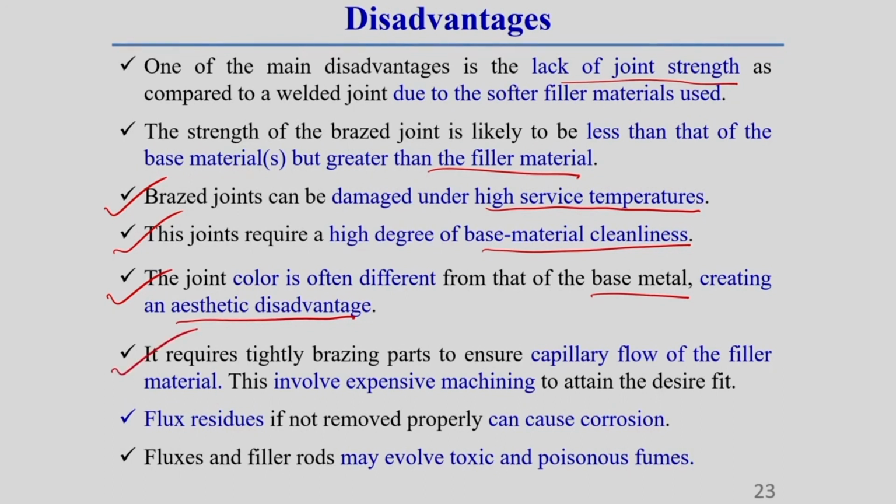It requires tightly fitted brazed parts to ensure capillary flow of the filler material. That is why this involves expensive machining to attain the desired fit. So, very expensive or very high quality machining is required for the brazing operation, because here a better joining tolerance should be there, so that better capillary action occurs.